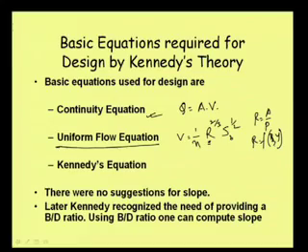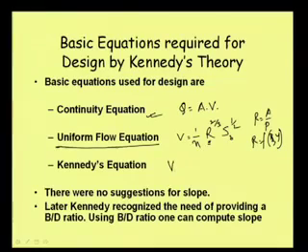And then of course, our main equation for design of the canal, Kennedy's equation, will be required, that is V0 equal to 0.55 m d to the power 0.64, and this is in metric units, that is, d is in meters and V0 is in meters per second.